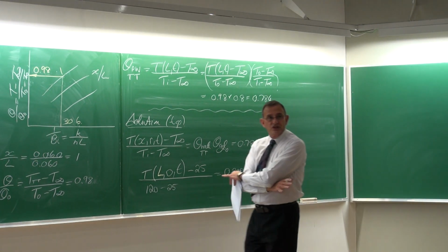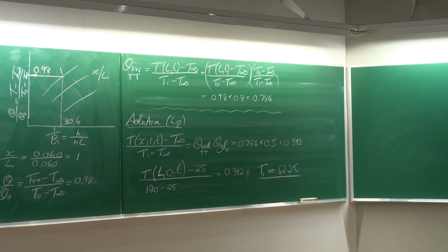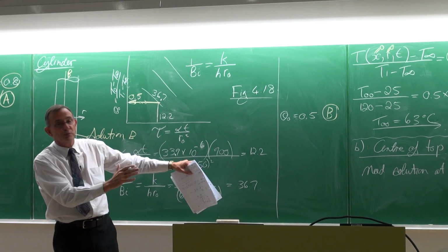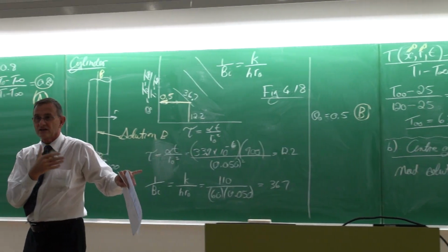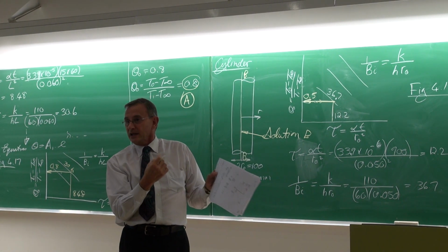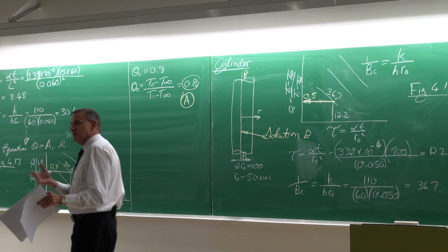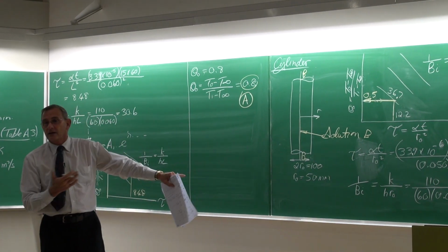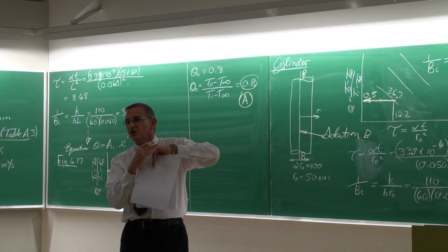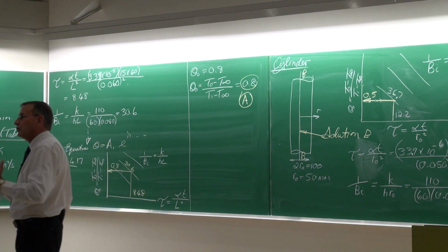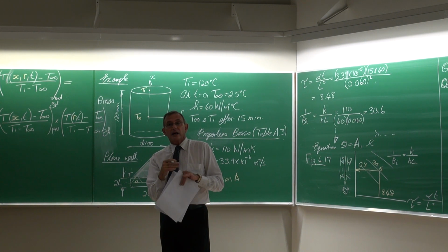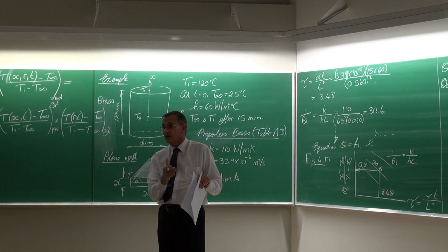Two more things that are important here. Again, I want to emphasize that I've used the Heisler charts because I don't want to put too much mathematics and calculations on the board, because it's going to distract you from the principle. You need to understand the principle. In the tests and exams, unfortunately, most probably you will have to do the calculations. You'll see on the Heisler charts, in many cases, the lines are so close to each other that it is impossible to get a very good solution. But the Heisler charts, in many cases, can be used to check your calculations.